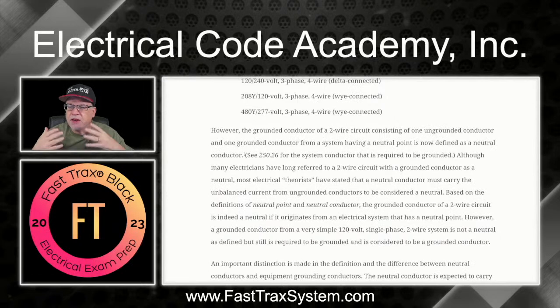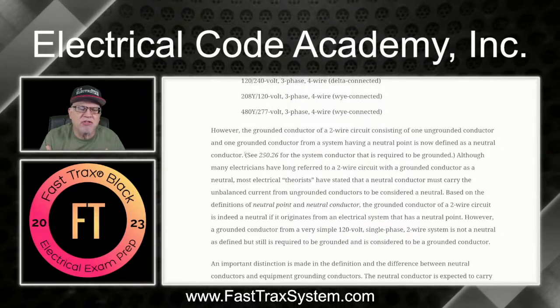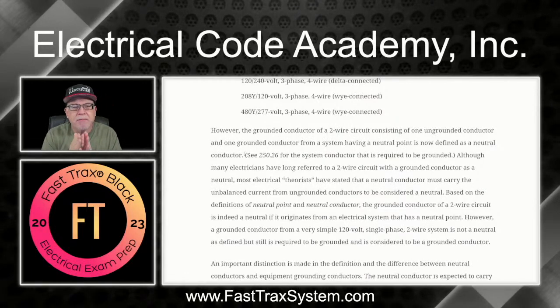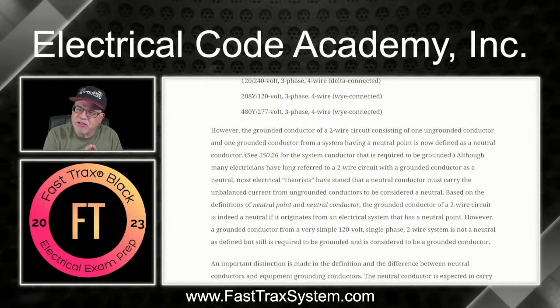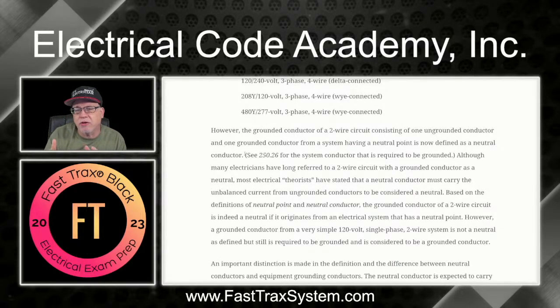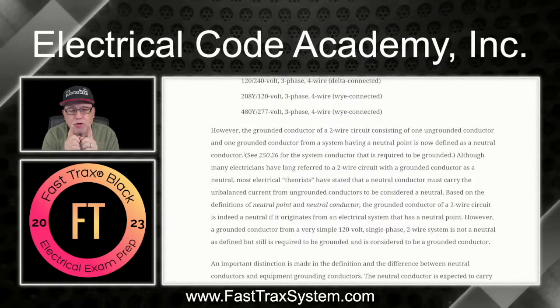So the theorists still will say, yeah, but it's not carrying the maximum unbalanced load between phases. It can't be a neutral. Well, because of its connection to the system, and that's a grounded system, because of these definitions, it's now considered a neutral conductor, even though it's more properly termed a grounded conductor.